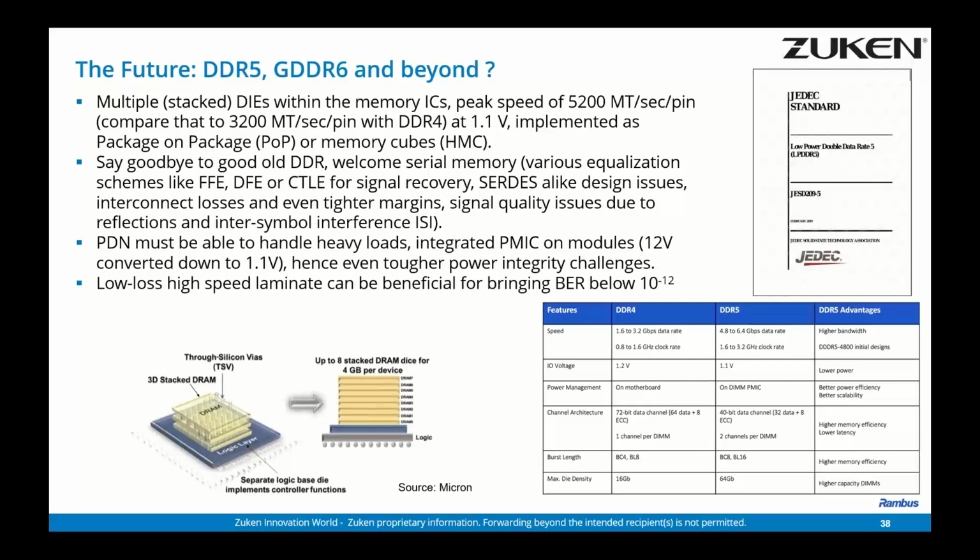So we have technologies with equalization on the driver side. That's already known in low power DDR4. But we have as well signal recovery on the receiver side, as we probably may know from SerDes technology. So we have things like FFE, DFE, CTLE. So more possibilities, more features, which unfortunately define more challenges in the design process.